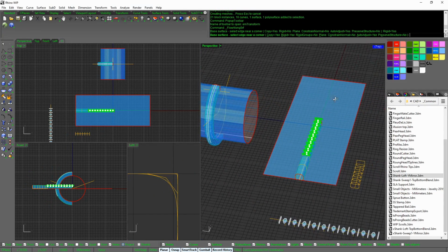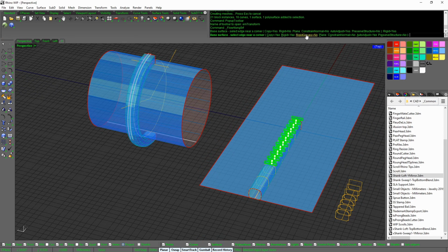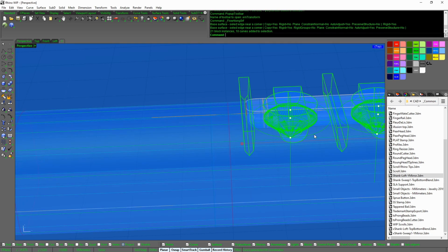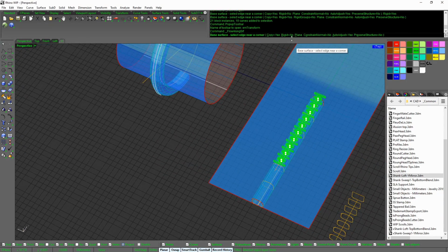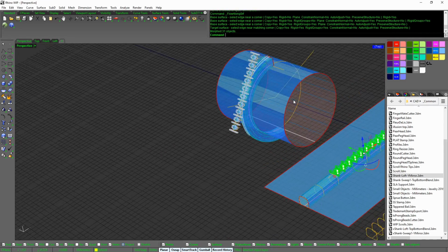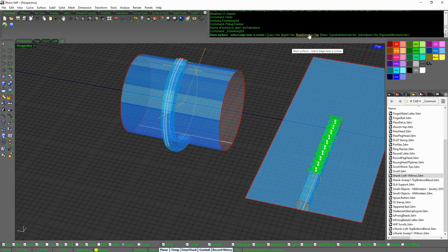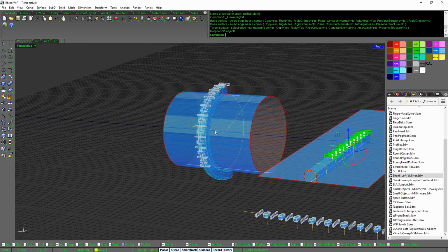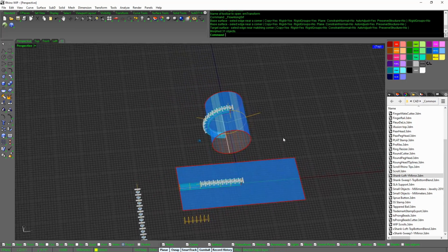I'm going to pause right here just to show you this. I've got rigid yes and rigid groups no. This takes it back to the Rhino 5 behavior, where you could take all of these things that we want to flow along rigidly, instead of the Rhino 6 behavior, where rigid groups was a thing, and it all showed up as 1, and then we can't use groups. Now we can do rigid groups no, and they're going to flow along as individual objects. Okay, back to the speed through.